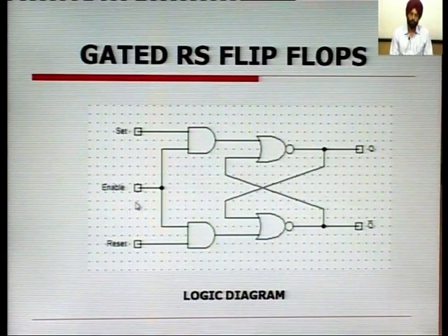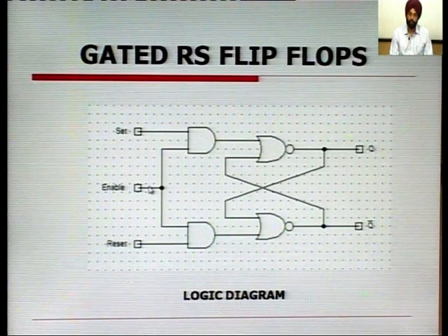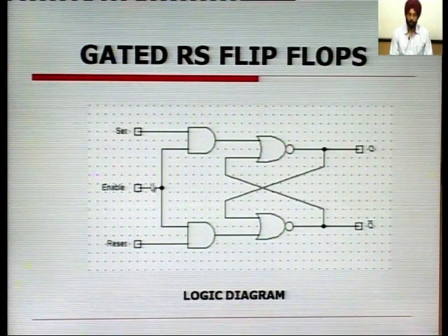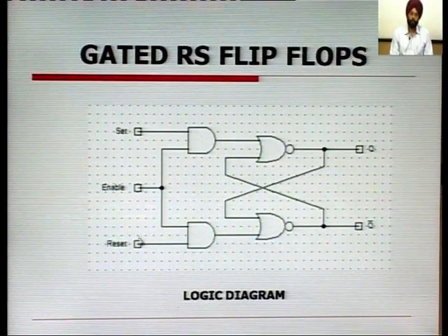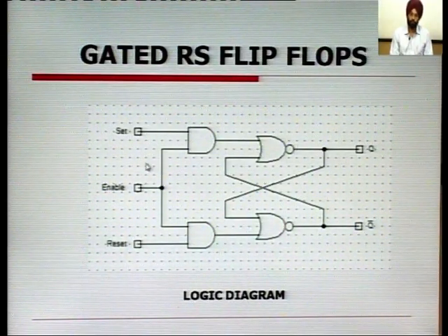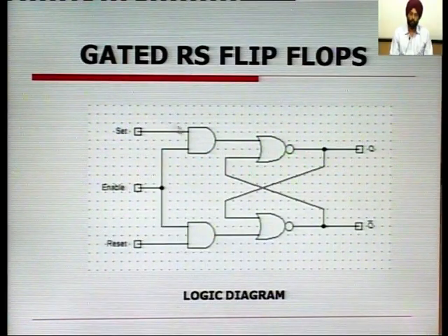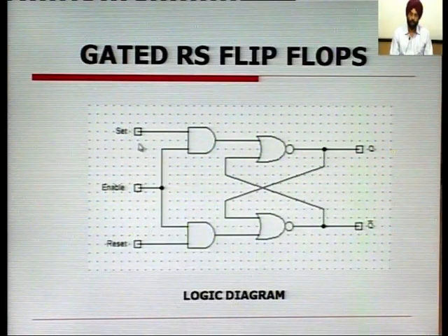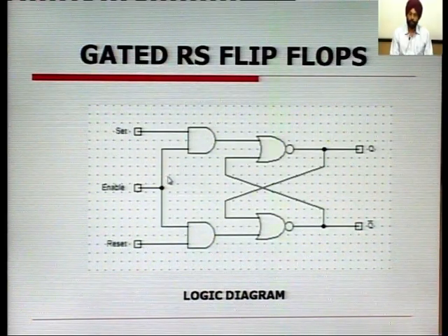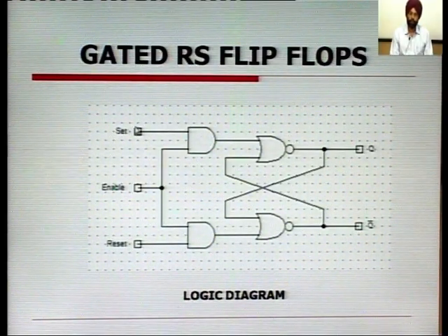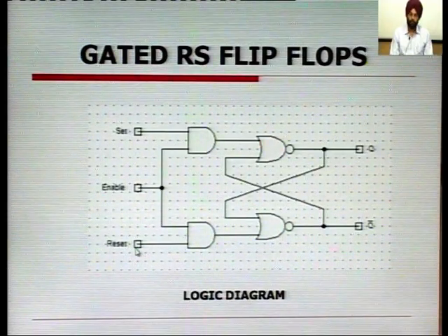But if the enable input is in the low state, or we can say the flip-flop is not enabled, in that case the inputs on the set or reset will have no effect on the working of this flip-flop, or on the output of this circuit, and it will stay in the last state even if set and reset are changing.